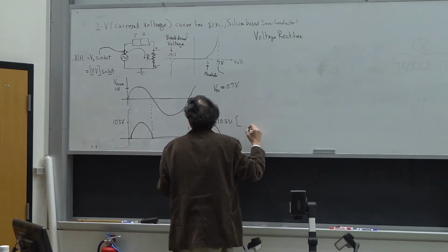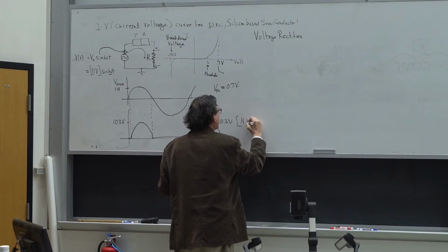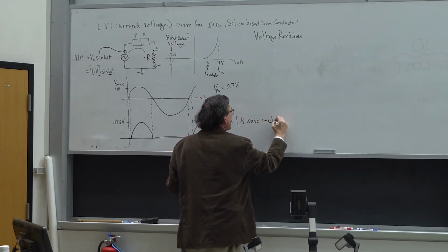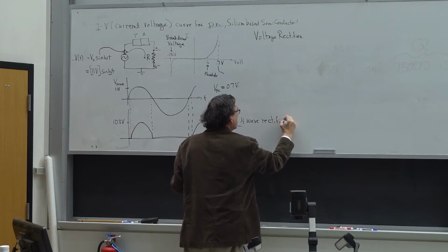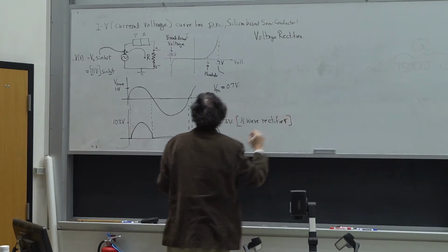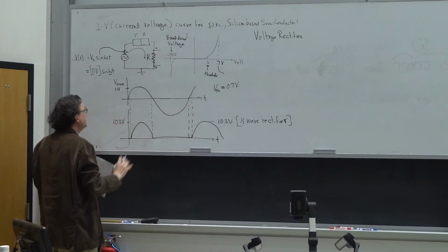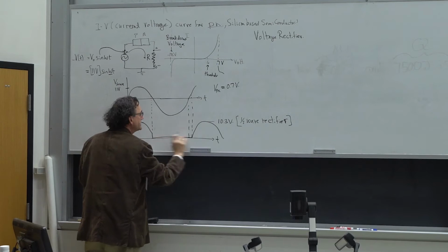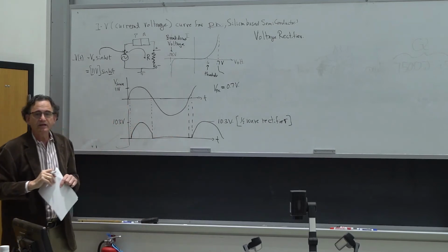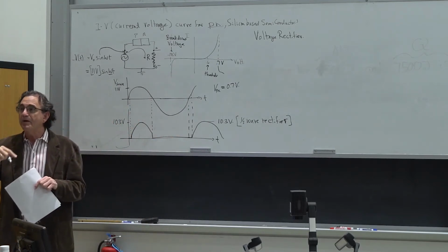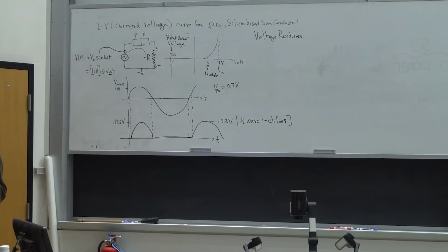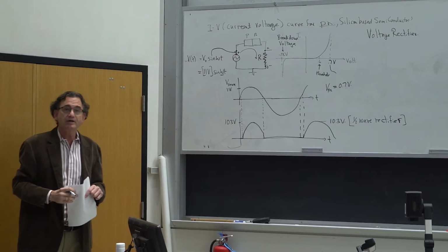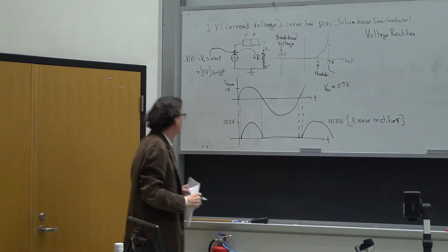So this gives us a general picture of something that this particular type of voltage display is called a half-wave rectifier. Half-wave rectifier because it maintains the positive part of the voltage cycle, but it takes out the negative. So I've basically now converted a bipolar voltage source to a single-sided voltage source.